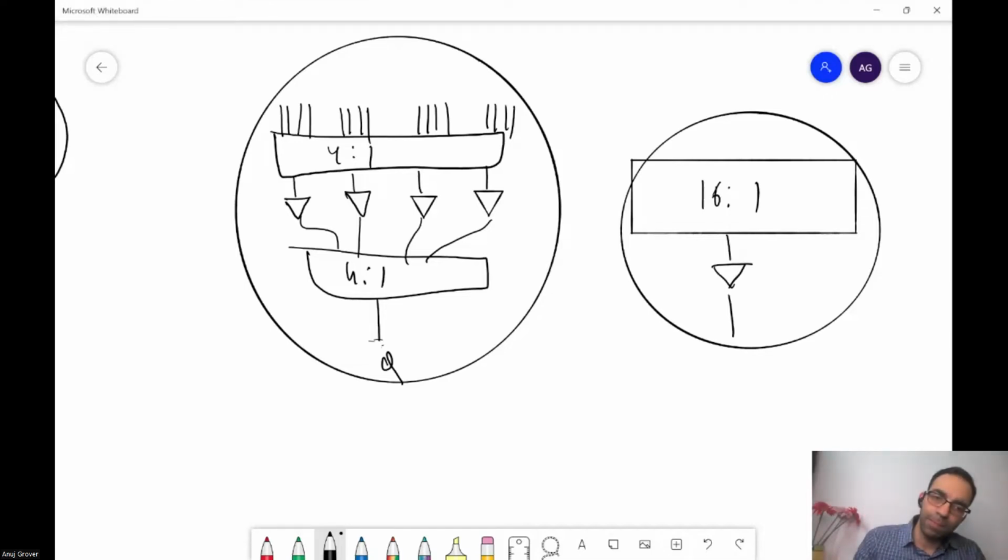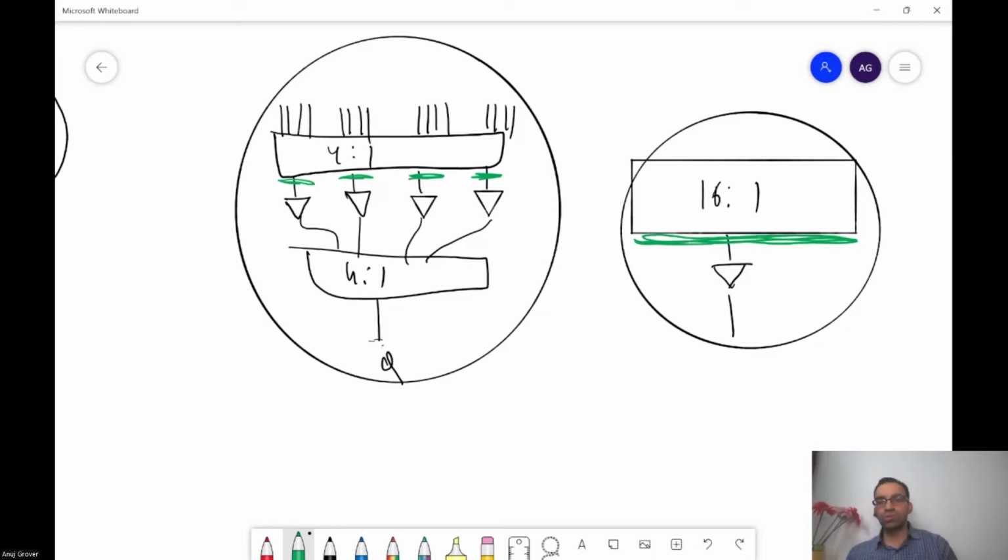Because the mux is divided into smaller parts, so the loads will be less. Yes, the load is only for 4 pairs of bit lines. Over here, there is one big load of all the bit lines. This signal runs horizontally. It's a huge load, so it becomes much slower.